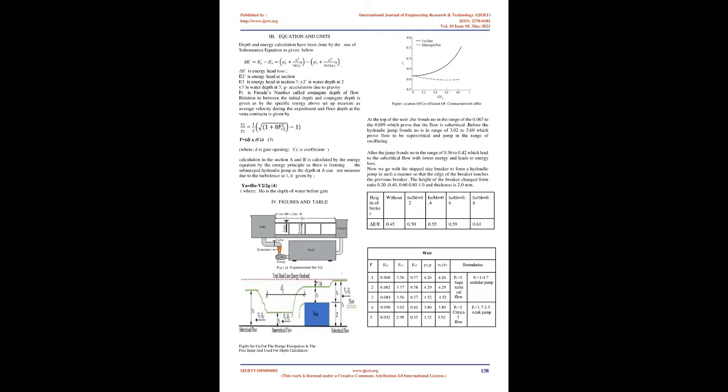Water is pumped from storage to the water collector tank, as shown in the figure. Discharge is measured with the help of velocity and area measurement of the flume. Also we can measure it with the help of a rotameter, which we can install at the outlet. Froude's number is varied from 3 to 9.5, up to the steady flow condition.